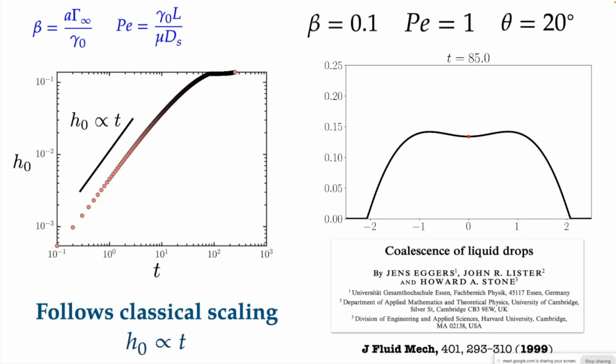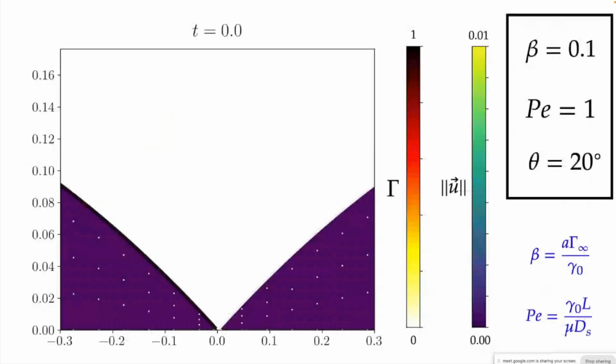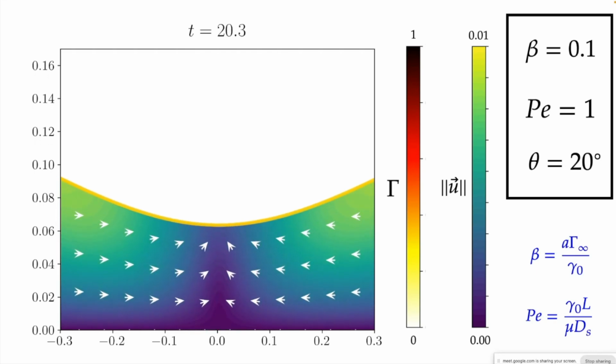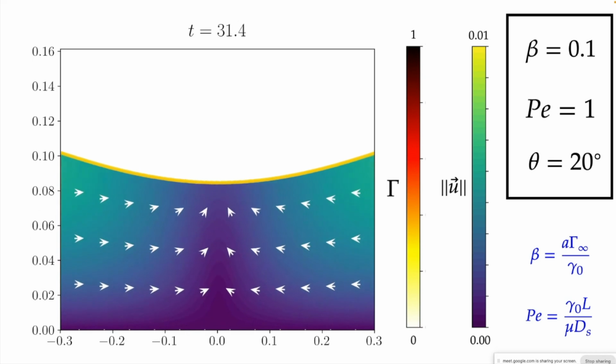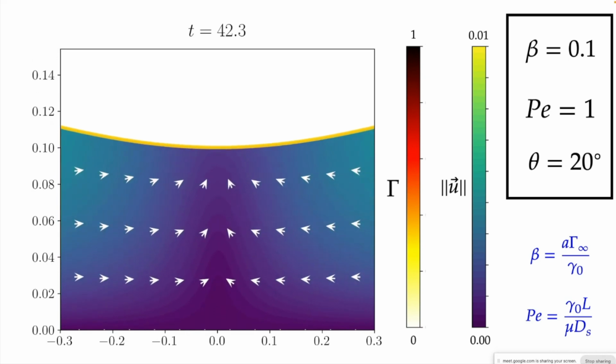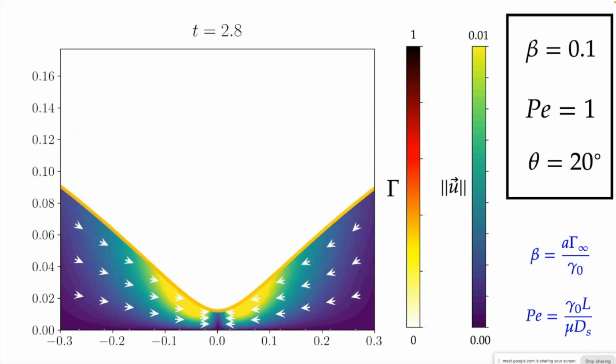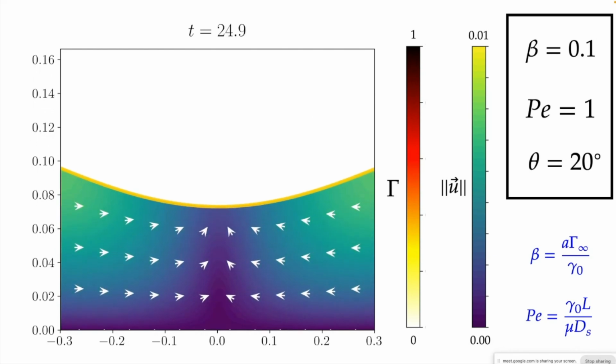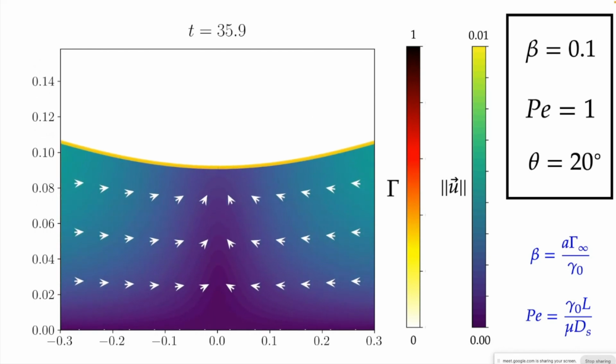So for this, we plot these velocity vectors, and on the interface, I put the surfactant concentration. So one is black, and 0 is white. And as you can see, it instantly diffuses, and your flow is directed towards the right, towards the neck, and it just moves upward. But one thing which is indispensable here is that you start out with this 1,0 profile, and it diffuses to this half value, which is 0.5.